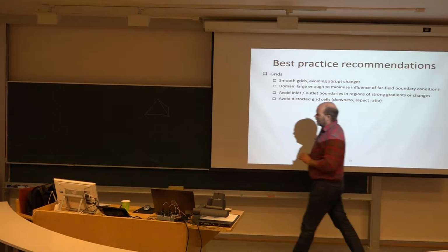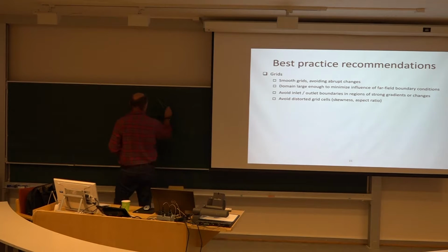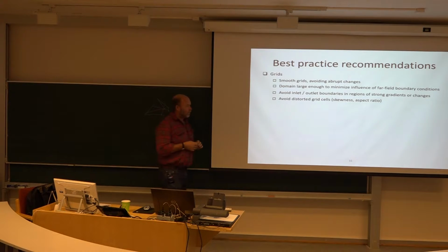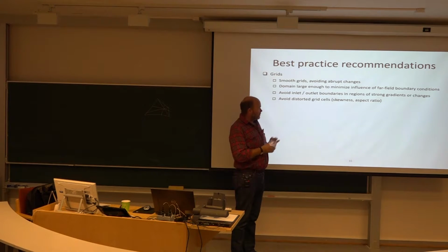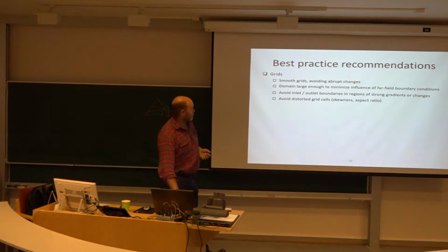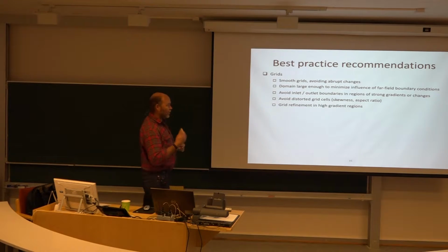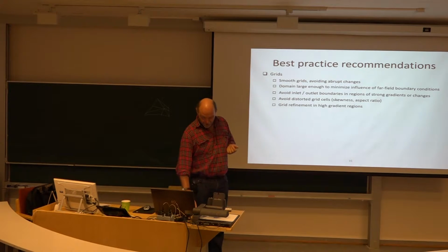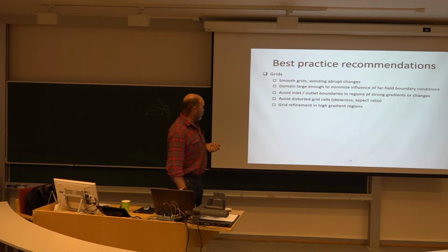So here I would then have split it up actually into more cells, at least better, maybe even something like this, to have a more smooth resolvement of the space. Also remember this correction number that we had for meshes when they are not perpendicular, all the mesh lines.